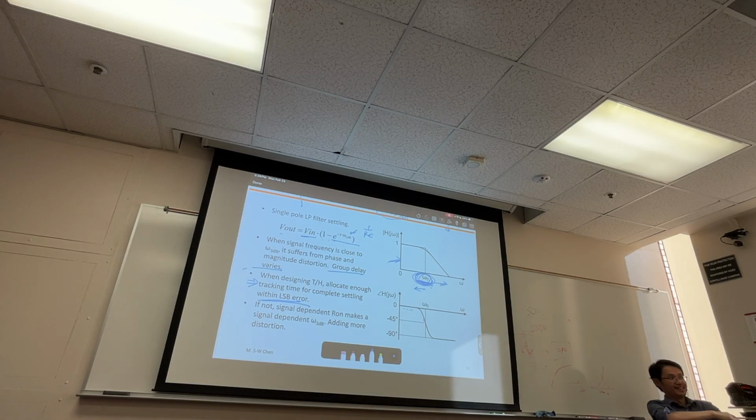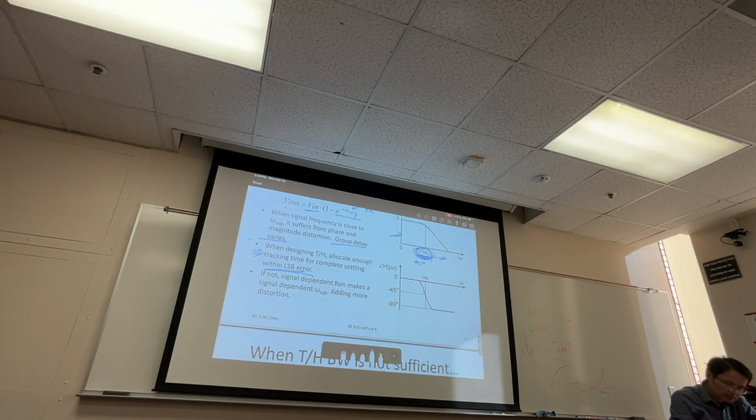Is that good or not good? It's not very good, right? Because you want to keep your pole frequency as high as possible. Whenever you go low, you cause distortion, you cause a settling issue, you get all those nasty things. So essentially, if you don't keep it constant, it still depends on the V value. Sometimes it will be higher, sometimes it will be lower, and you really worry about the lower bound. So it will vary.